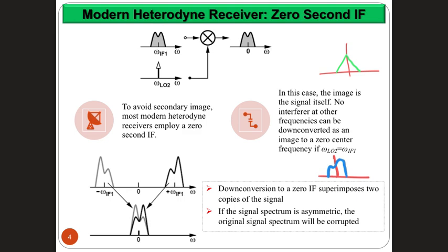Right. I'll come to you. I'll answer something that he said and come to you because you want to answer as well. So rethink your answer, because here I'm talking about two signals around 0. So we are not moving up or down in frequency. This is the baseband signal. Yes? When the function is really not complex. Yeah, that's the first case. Yeah, it's symmetric. Yes, and in the second case, it's complex in the time domain. Yeah, exactly. So if the signal in the time domain is complex, you will end up with something like this. If the signal in the time domain is real, meaning x of t is real valued only, you will end up with the symmetric situation. That's the correct answer.